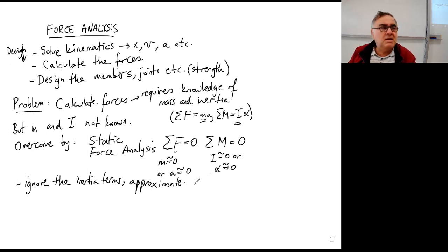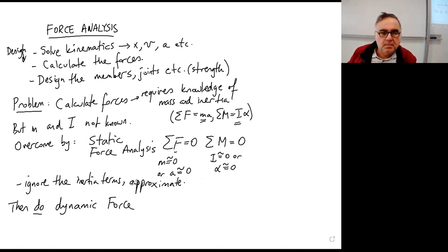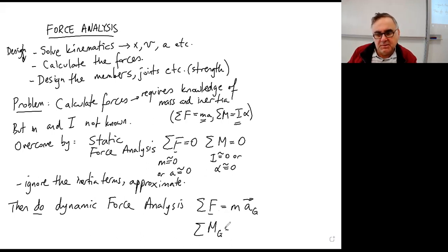So you usually start by static force analysis and then do dynamic force analysis, which is summation of forces equal to m times a, the acceleration of the mass center, as we know, and the summation of moments about the mass center is equal to Ig times alpha.